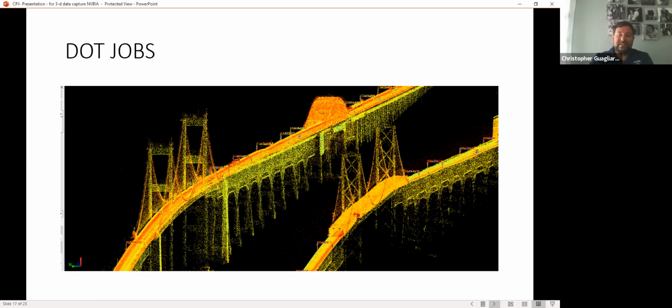So you figure I did it in less than an hour. It really saved a lot of time, and it was very safe doing that as well. So that's another benefit of these scanners and these mobile scanners, is that it's safe. And you have to just make sure when you're doing a model grade or these scanners that you tie it into survey control, which is very easy.